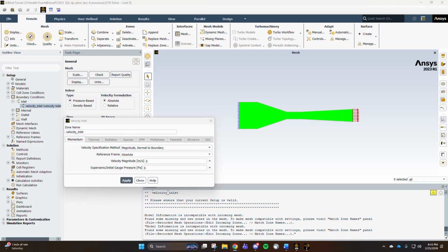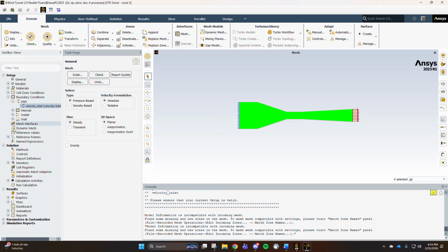So I will be doing the 20 hertz level of this equation. And with this equation, when we calculate it at 20 hertz, we get 4.6062. However, that is the test section velocity, and we need to give it the inlet velocity in order to get this at the test section. So what we do with this number is we divide it by the ratio, which we've been given just the height of the beginning of the contraction chamber and the beginning of the test section, which is 22 inches and 6 inches respectively. So we times it by the height of the test section and then divide it by the height of the contraction chamber entrance, giving us a ratio, and giving us an answer of 1.256236364, and we're going to just do it exactly how the calculator says. So we're going to apply that, and that is our inlet velocity.